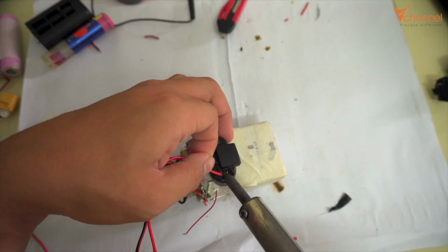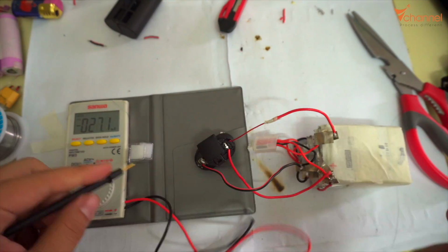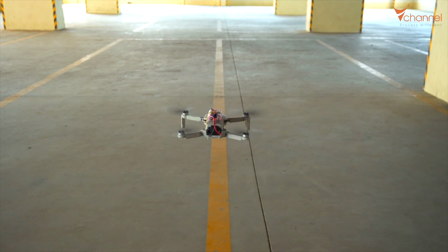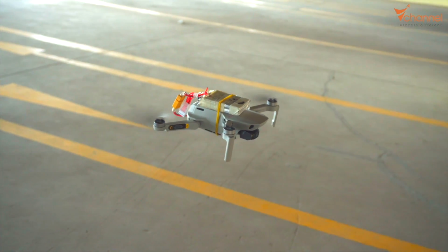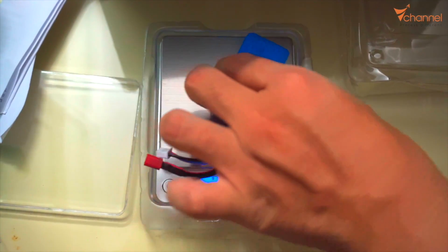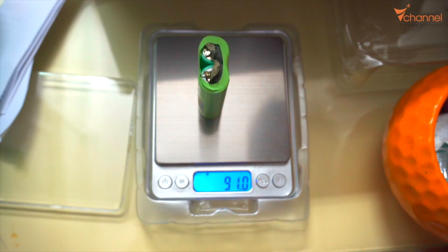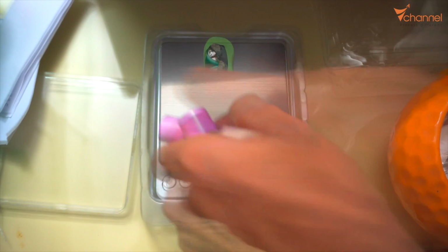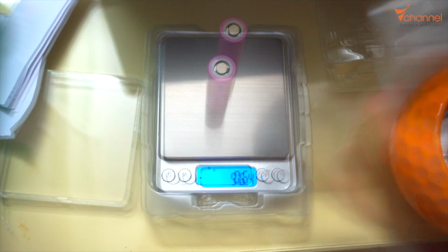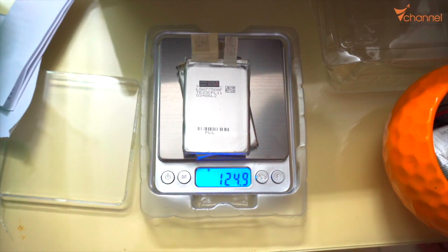About drone battery modifying, although in theory, when we connect two batteries in parallel, we will have double the capacity and can have double the using time, in reality it's absolutely wrong. Because when combining batteries, the drone has to carry the new weight of the battery, so it will decrease the flight time. So in reality, when modifying a battery for a drone in general and for the Mavic Mini in particular, we must calculate the best relation between capacity and battery weight to get the best flight time.